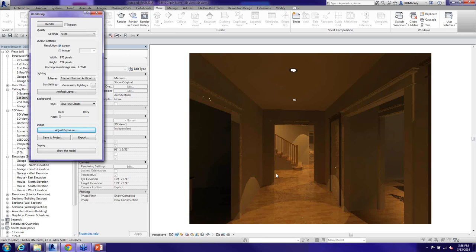So you guys can kind of see, you're doing this. And yeah, somebody did say to make sure your Revit always has the latest service pack, because the cloud rendering is always working off the latest service pack for the Revit models.